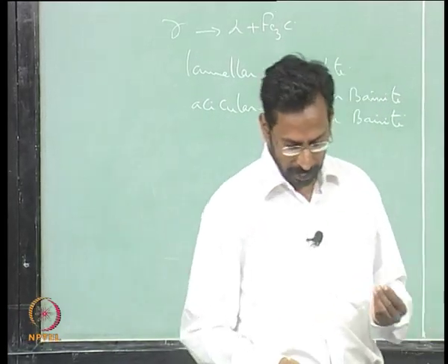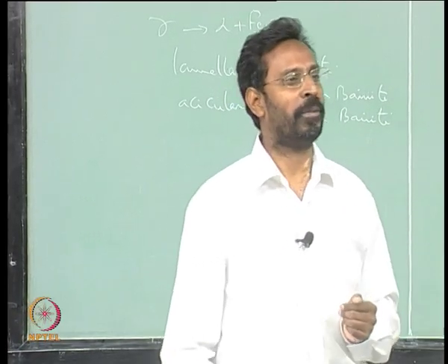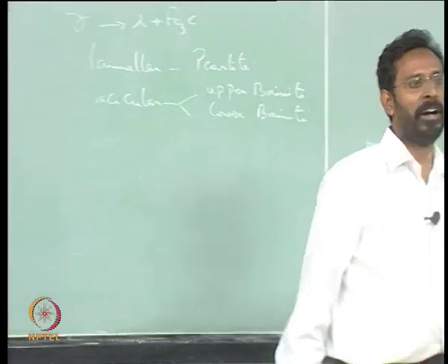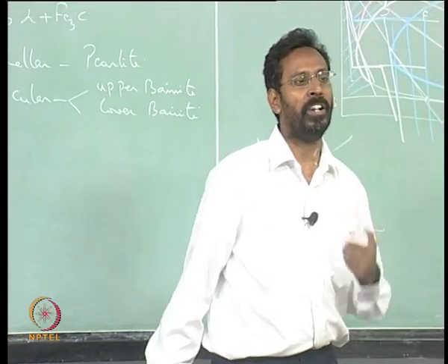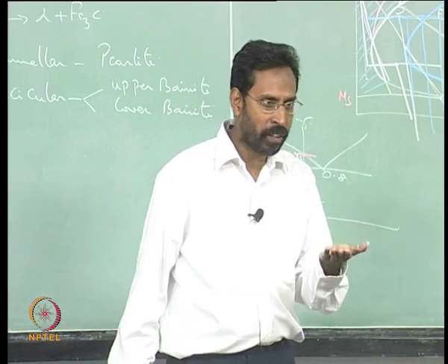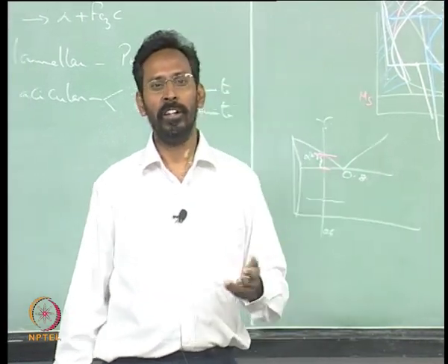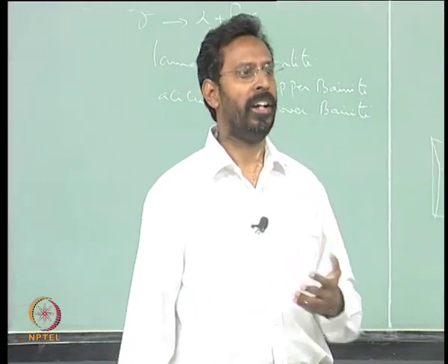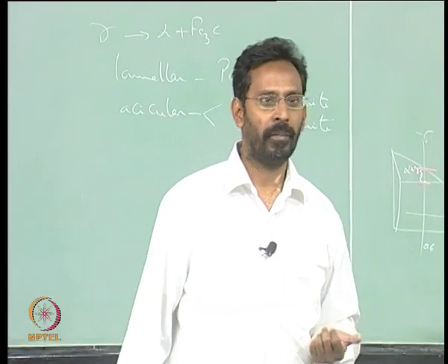Yeah, this is when we come to Martensite we will talk about it, okay. So there is also always something called deformation induced Martensite, okay. You can, the MS temperature can go up. All of us know that MS temperature, whenever you add alloying elements it always goes down. Why does it go down?